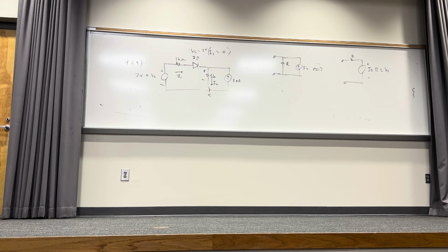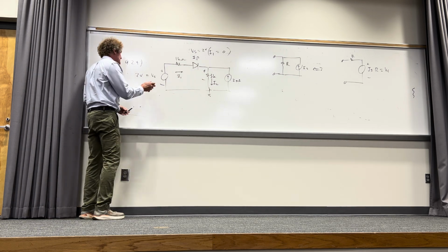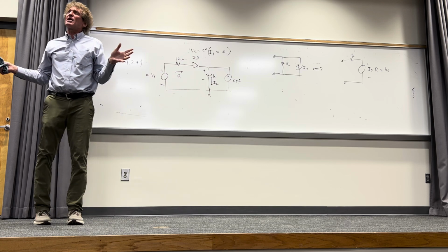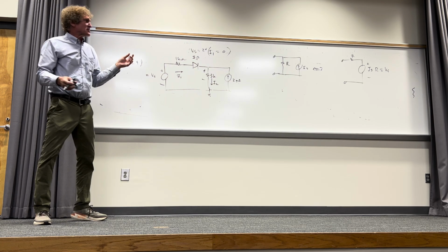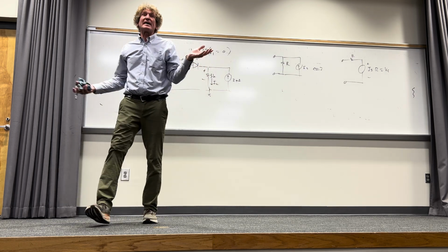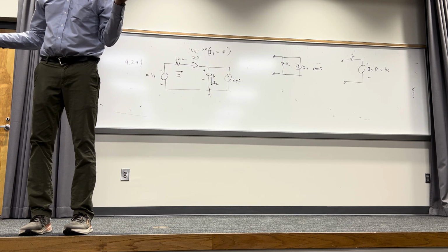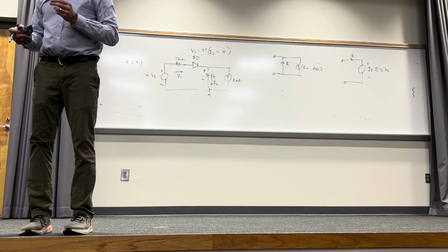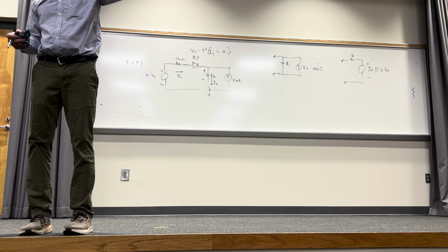Now, next question is this. So Vs for the second part, and we can do non-ideal in a second. Now, if it's non-ideal, is it going to matter for that case? It doesn't matter if I have a threshold voltage to overcome. I can't even get the thing going if it's ideal. So the threshold voltage stuff you can throw out. Ideal or non-ideal, no current flows when Vs is 2. How many see that? Down here, guys?